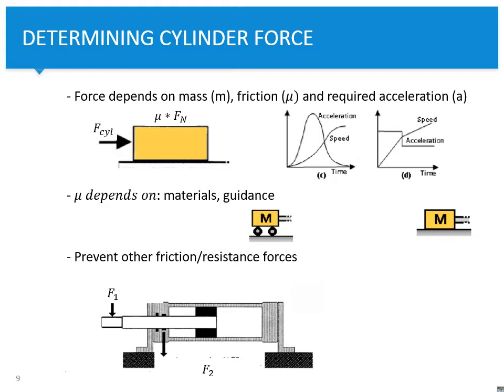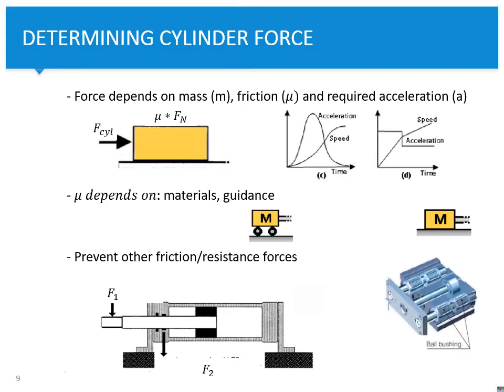So over here you see that the force F1 at the end of the cylinder rod causes force to the seals and scrapers and whatever is there in the cylinder head. And may cause some moments as well, I'm not sure. So proper design for load case can be very beneficial for the design of your cylinders. And this can be solved, for instance, using this method.